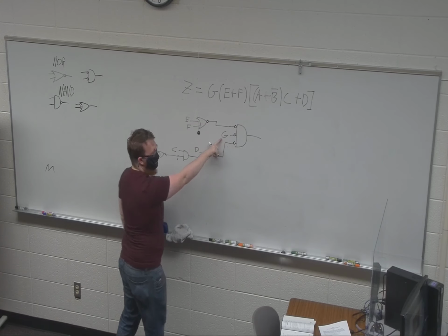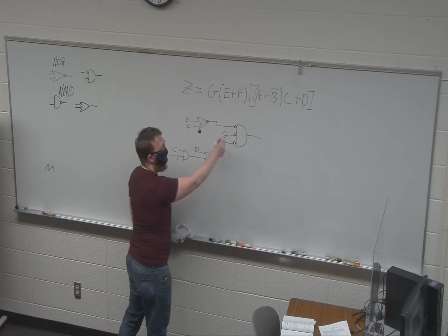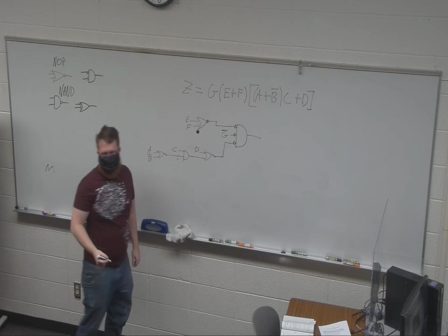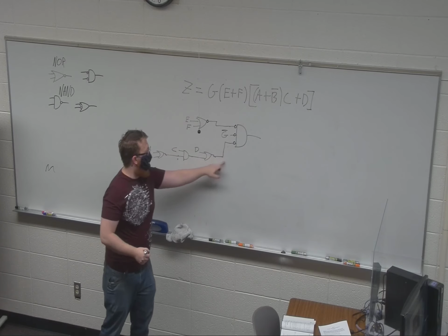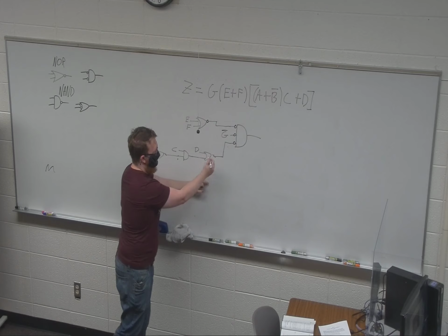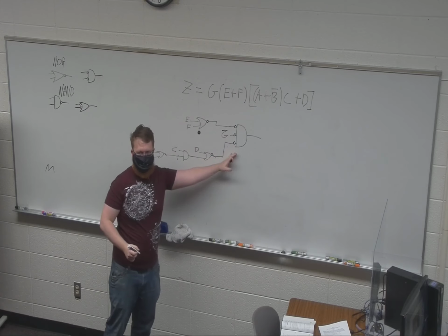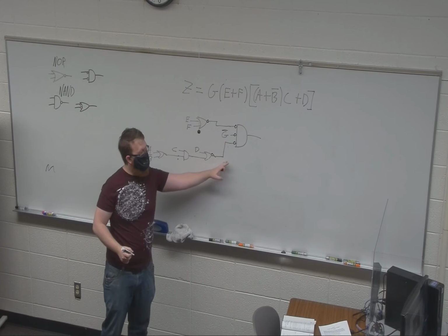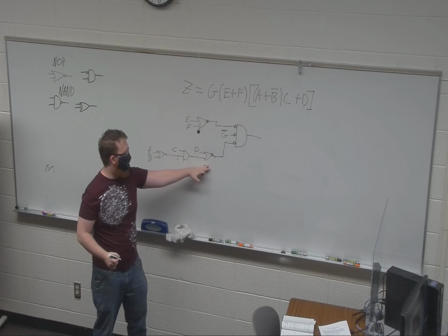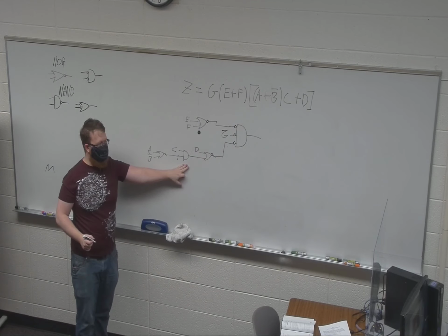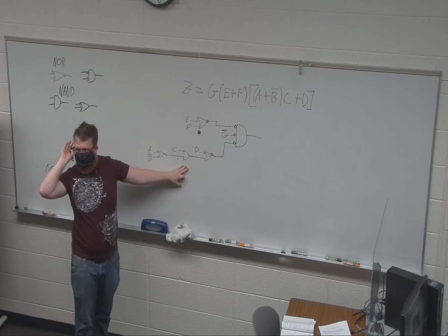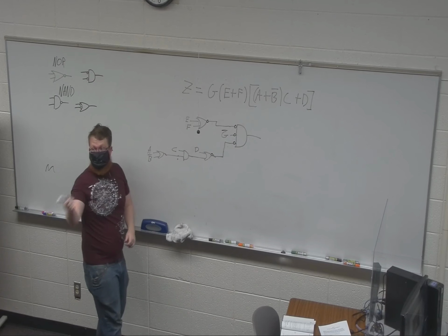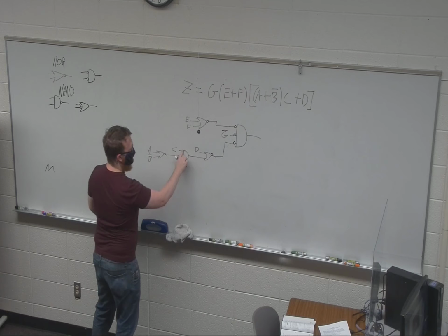And then, what do I do with the G? Yeah, I mean, we're going to say NOT it, or we can throw an invert into that input. Coming through, we need, again, to double invert to make sure that we stay the same, but end up with, again, another NOR gate. All right, what do I do here? I make it a NOR. NOR, how are we going to do that? Bubbles on the left side. Yep, perfect.